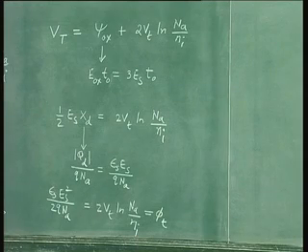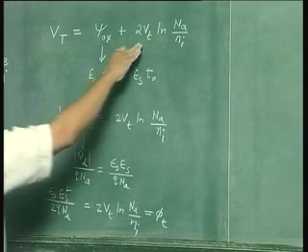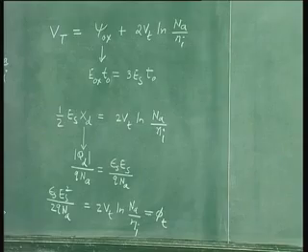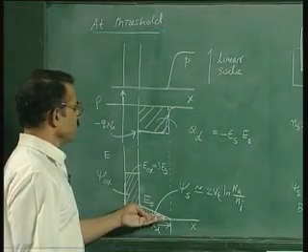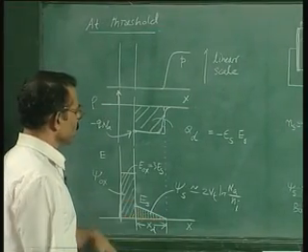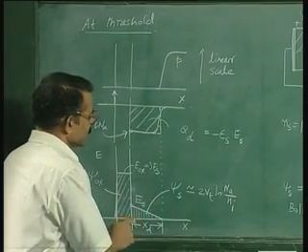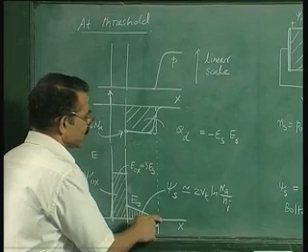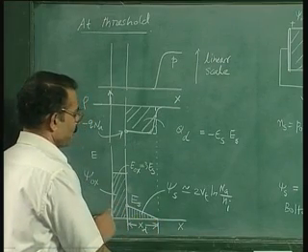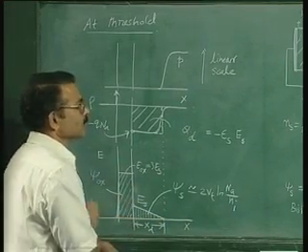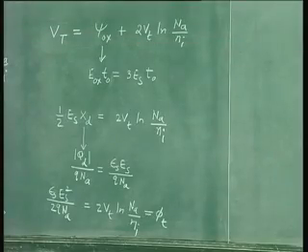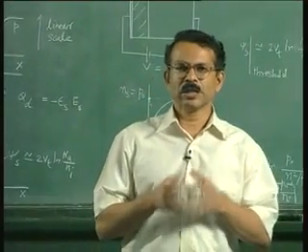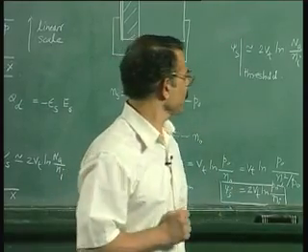Note that the potential drop in the semiconductor, that is psi s, that is this here, is also referred to as surface potential, because this psi s is the potential of this point with respect to the bulk, and this is the surface. So that is why it is called surface potential. We are assuming that the bulk potential is 0 in the semiconductor reference.